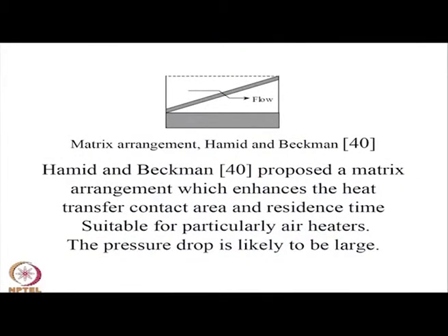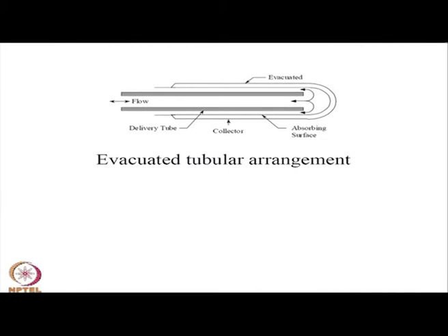You can increase the pressure drop and not gain the corresponding increase in heat transfer. So, that is like you can imagine a pipe, you put a plug at the end of it, the pressure drop will be enormous, but there will be no significant improvement in the heat transfer.